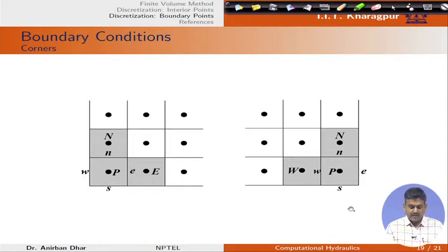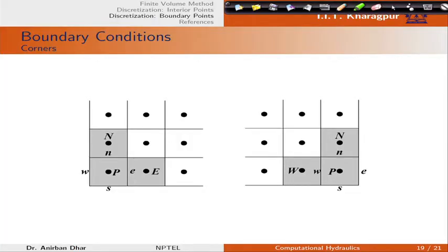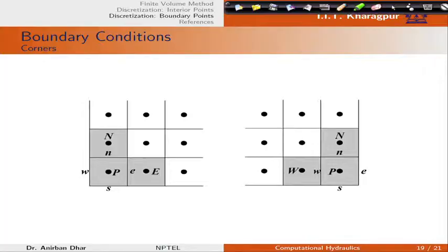So with these discretizations, which are similar to your boundary value problem, we can get the discretized form for all the cell center points, solve the final matrix, and get the values for all cell centered positions. If you have a Dirichlet boundary, your boundary values are specified, but for a Neumann boundary we can utilize the nodes or cell centers next to our boundary to get information about the value at the boundary itself. Thank you.